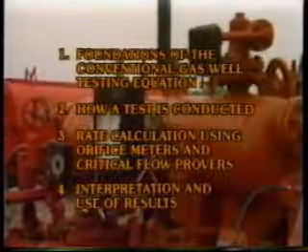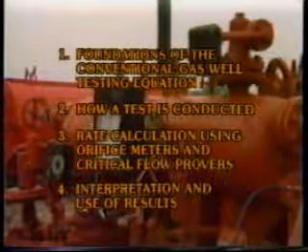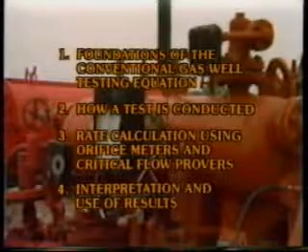From the exercises you've just worked, you should have learned the foundations and basic assumptions of the conventional gas well testing equation, how a test is conducted, the manner in which rates are measured using orifice meters and critical flow provers, and how to interpret and use the test results.